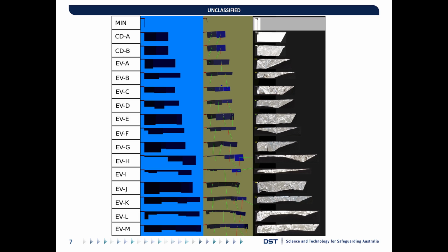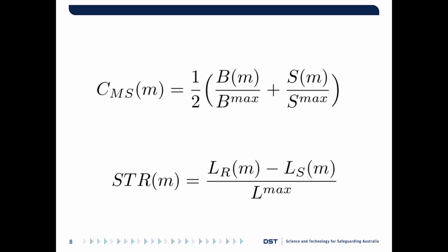For all the designs we transferred, we measured two quantities. The first was the complexity measure for the simulation robot, derived by the size and number of blade elements used in the simulation environment. The second is the Sim2real disparity, which is the difference in lift between the real and the simulation wings. Both of these variables are normalized by the maximum values seen in the design process.